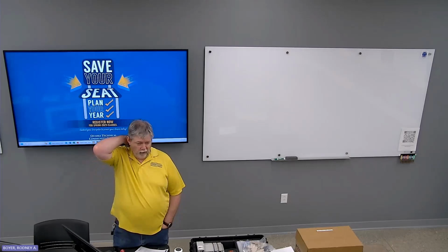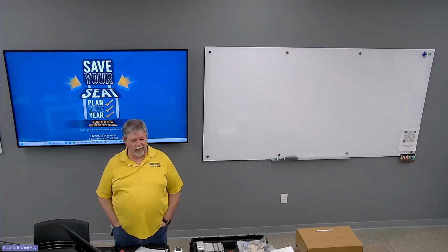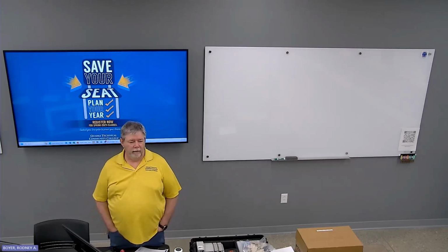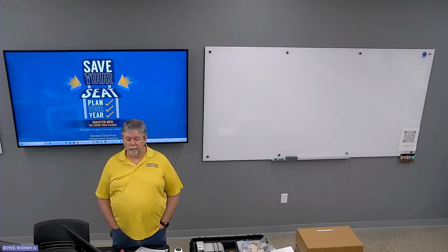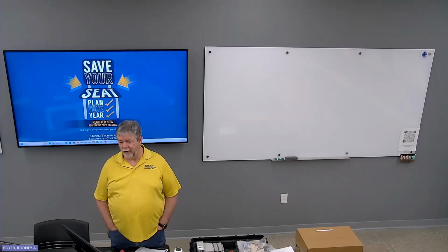But people being creative have come up with some really cool ways to lock things out. How in the world are they going to lock that out? Well, it may be something as simple as wrapping a chain around it so you can't move it. We started doing at work that if you open a door, a little metal piece comes in so you can't reclose it. Presumably those doors have an interlock switch that breaks the safety circuit and shuts it down anyway.